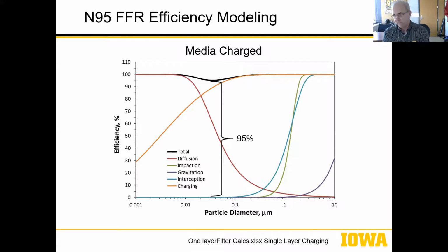So now we know for sure that it varies by size, but that at its minimum, it's at 95. So these things actually are way more efficient than 95%. I hope that's what you're getting out of this, especially for anything larger than 1 micron, which is the large majority of particles out there in industrial situations. Even large bacteria are up here on the right, and so they are capturing just about everything, as long as there's no leaks. So it's not quite like this, though, in reality.